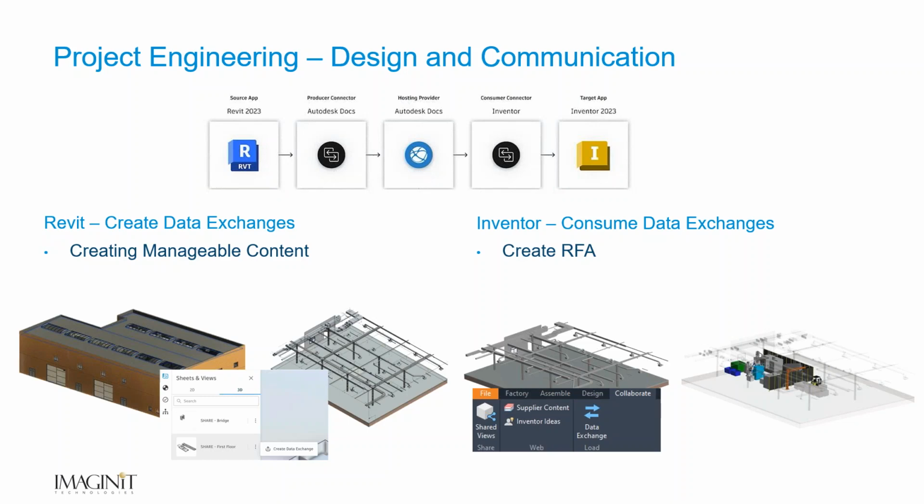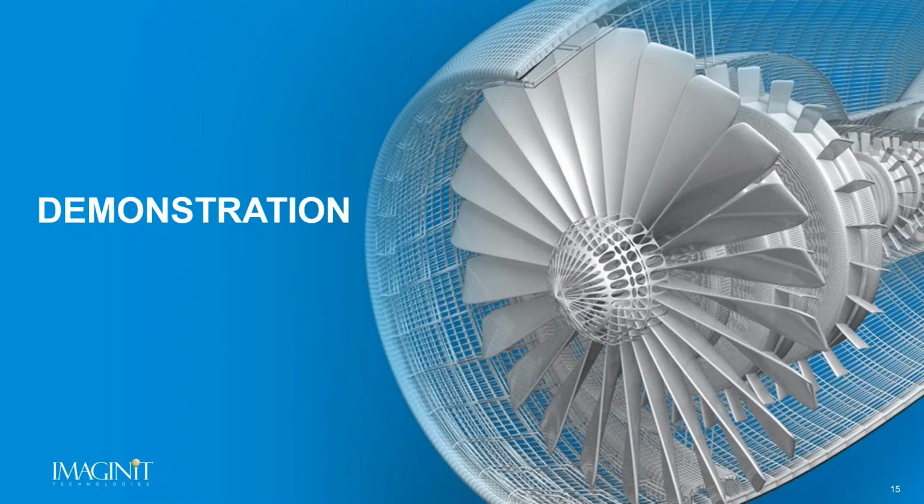Yeah, with the data exchange, my Revit file exists up inside of the construction cloud. With that, I can give Caleb permission to see a specific folder, a specific location, or a specific set of files inside of the construction cloud. Once I'm happy and I've redefined that entire building down to a specific zone or area, I have the ability to create a data exchange file that's going to allow Caleb to just bring in what you're seeing, the columns, the ductwork, and the floor for those specific bays that are impacted by what Caleb needs to work on.